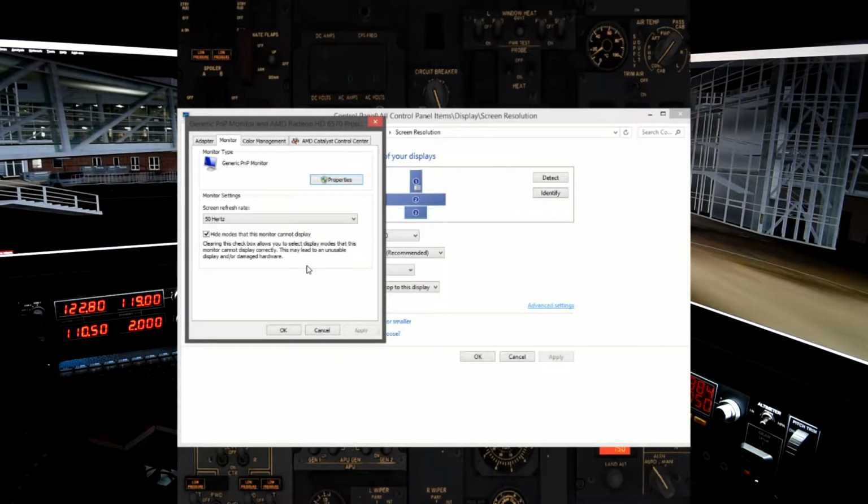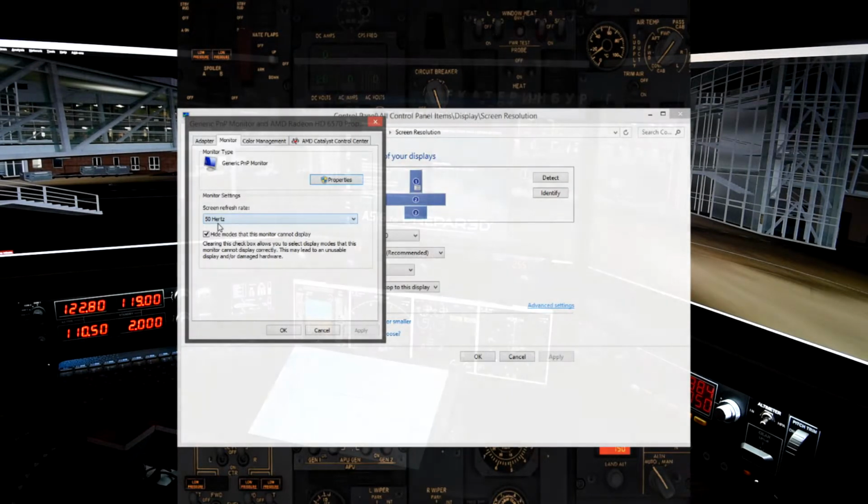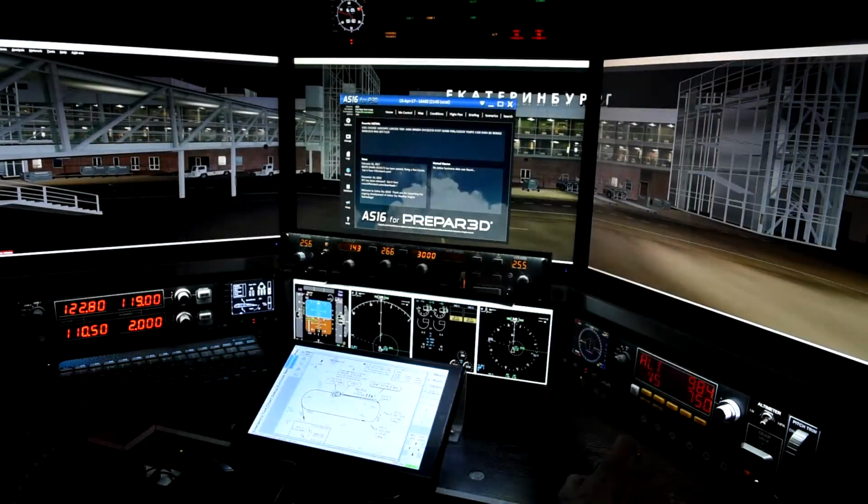The screen has strange purple borders, unusable areas, and so on. I think the reason is the AverMedia drivers, or maybe it's a problem with the software. Be sure, if you make this in your installation, the monitor plugged into the AverMedia card must support different refresh rate profiles. Then you will be able to find the right frequency profile.